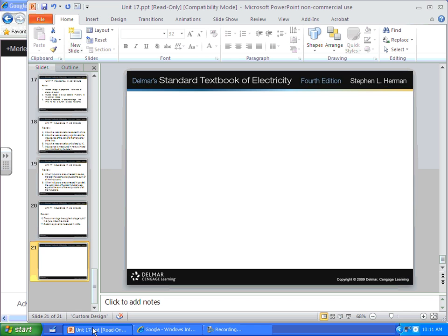Any questions? Yes, sir. I know other teachers like to teach the Pythagorean theorem. Don't. Stop. I'm glad you brought that up. Now, what are we doing here when we did those two different triangles? I have a name for it. I've created a name for that. Nobody else uses my name for it, but I don't care. I call it simultaneous triangles because they both have the same angle. It's called the phase angle. And the phase angle for any AC circuit is the same phase angle for any part of that circuit, right? The phase angle is the phase angle is the phase angle. So if we solve the resistance triangle and we use angles and we find the angle, then we can find the other triangle totals, right?